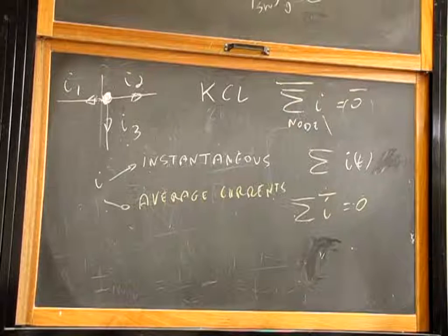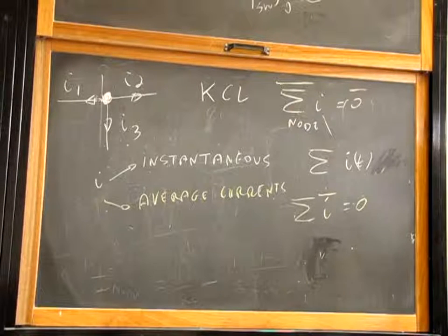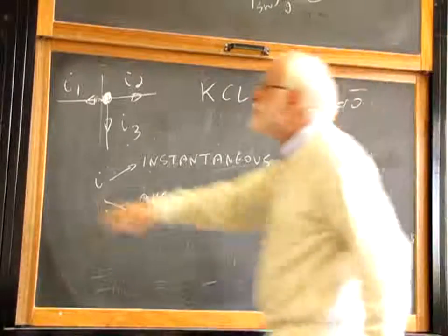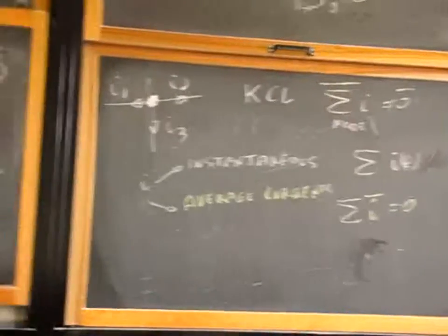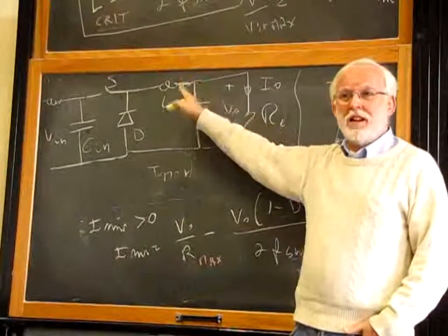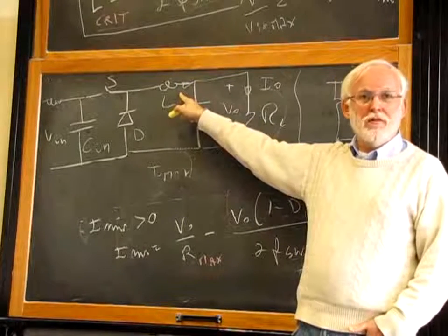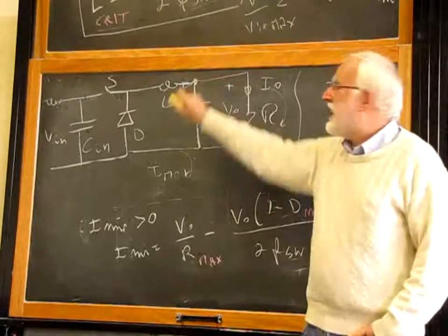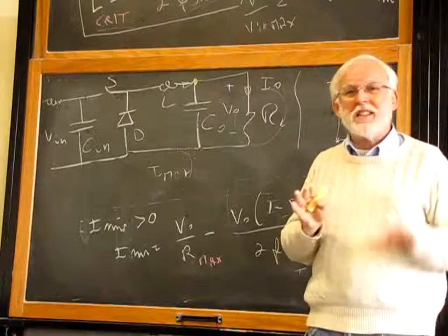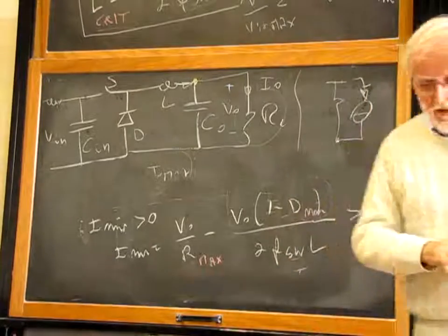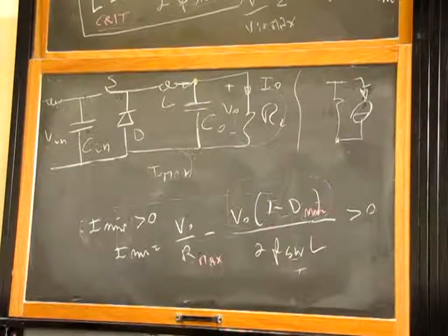And we already did it without pointing it out in the text, because when I told you, here I have a DC component and an AC component coming out from the inductor. Where is the DC component going to? You got me all through the load. You are applying the KCL to this node for the DC components. So you can separate DC components from AC components. Okay, so this is okay.